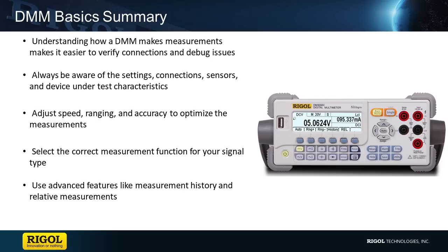And think about what that function is doing, right? Is this a short circuit I'm presenting to my circuit? Is it a high impedance measurement? Once you understand theoretically what it's doing, then you can figure out for yourself whether it's connected correctly or not, right? Should this be in parallel or series? Well, it's a short circuit, measuring amps, so I want to be in the circuit, for instance.